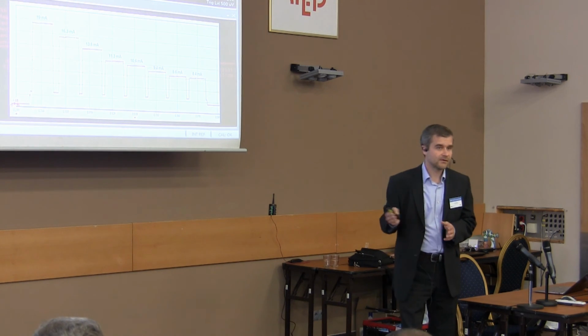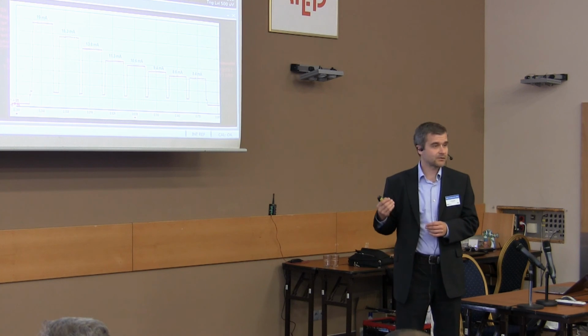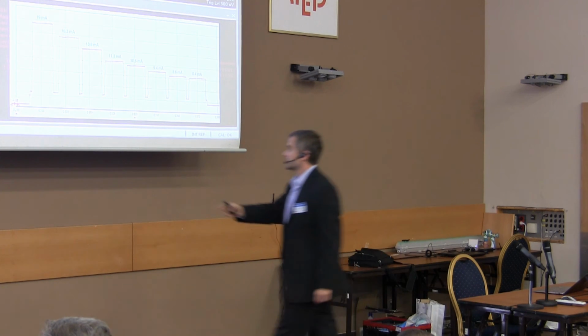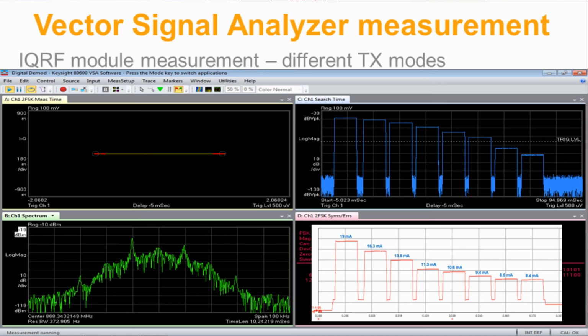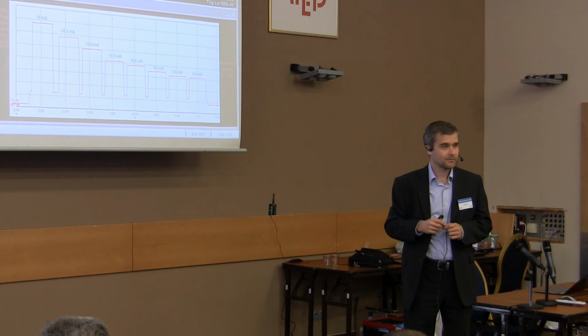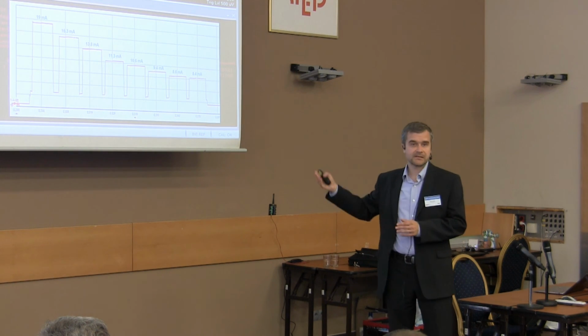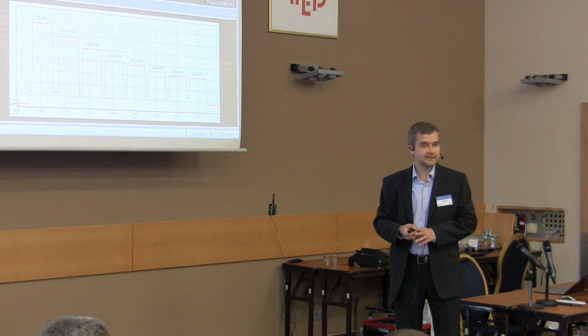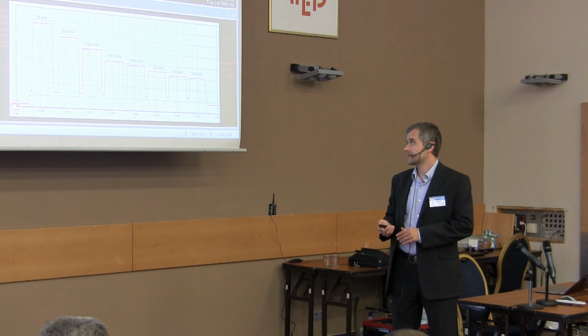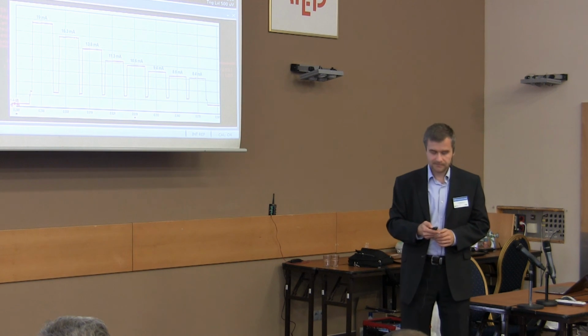It's better to use not the highest power transmission but a lower power, because the higher power is just a little bit more power, but the modulation is worse because of the saturation of the amplifier. So based on this, you can optimize your states very well, and it's a real example.